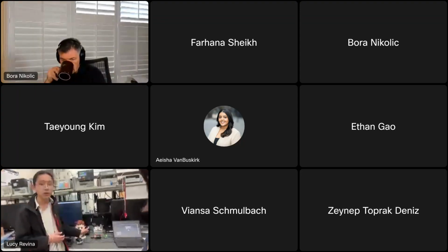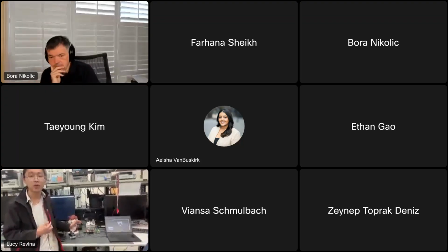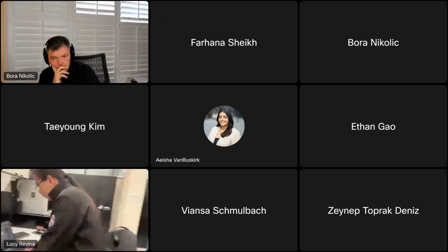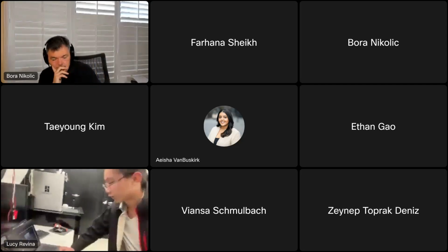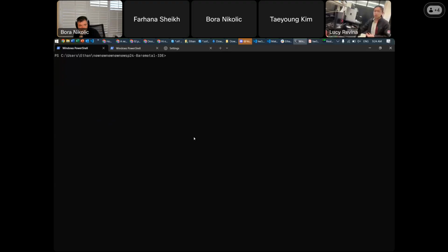In this case, this chip right here is going to be running a small large language model called TinyStories, which is based on the Llama architecture and the llama2.c file by Karpathy. So if I go to this laptop over here, we can see that in order to program the chip, we're using all industry standard tools. We're using GCC to build the program, OpenOCD to connect to the chip, and GDB to debug it.